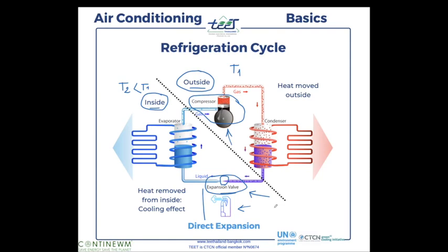And the temperature increases, we want to remove this heat, so that's what we call the condenser. So the condenser, the equipment is exactly the same as the evaporator. The only difference is that it removes the heat from inside the gas, okay, that is hot, high pressure and hot. It removes the heat to outside, okay? So that's why we have a fan that blows through the fin that looks exactly the same as the one inside the air conditioning, okay? And we extract the heat from the compressed gas, okay?